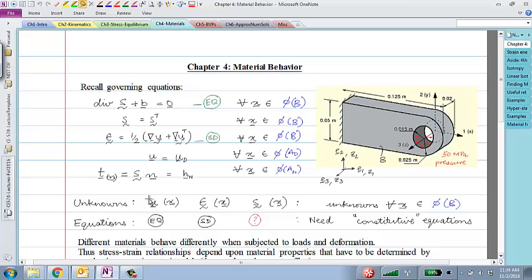There's a displacement field, which means you need to find the displacement vector as a function of x at every point in the deformed configuration, or actually z in the undeformed configuration. But that's just a slight difference where you express that displacement field either as an Eulerian or a Lagrangian variable.